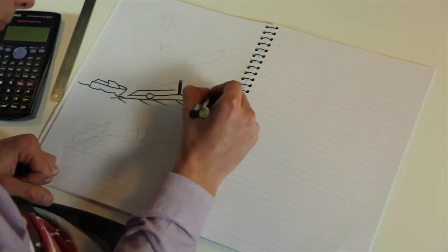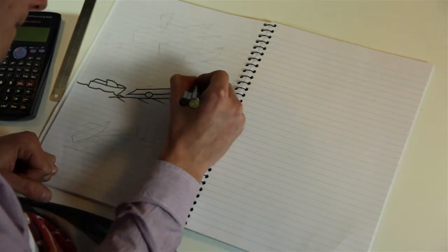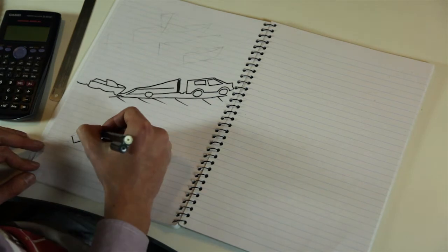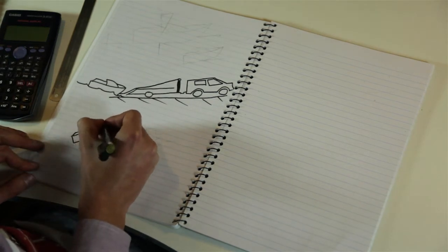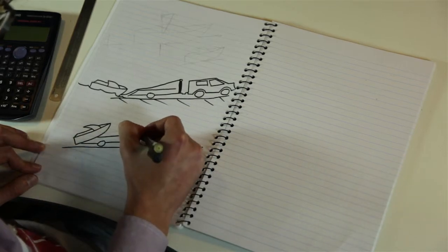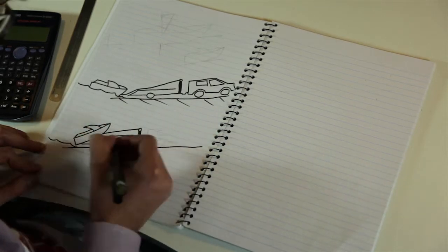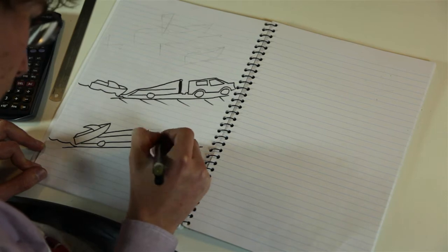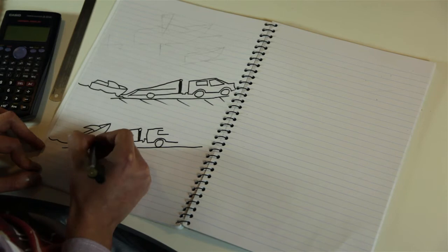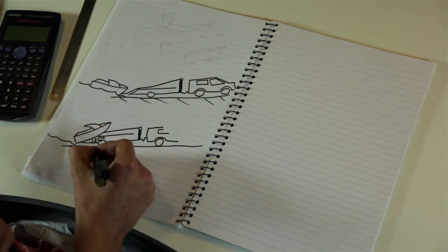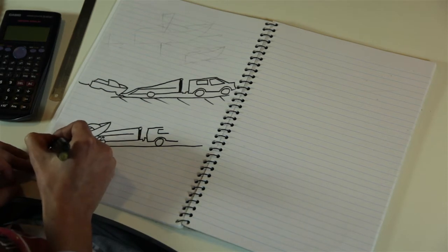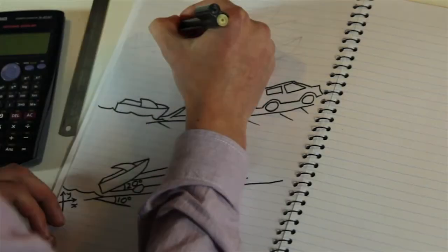Let's try an example. James is trying to pull his boat up onto his trailer. With the boat sitting stationary on the first section of the trailer, what is the minimum force required from the winching rope in order for the boat to start moving up onto the trailer? We'll assume a 1,000 kilogram boat, a static coefficient of friction between boat and trailer of 0.3, and the following angles. We state these angles relative to a set of coordinate axes. We'll also assume that the boat's center of mass lies along the line of the winching rope.